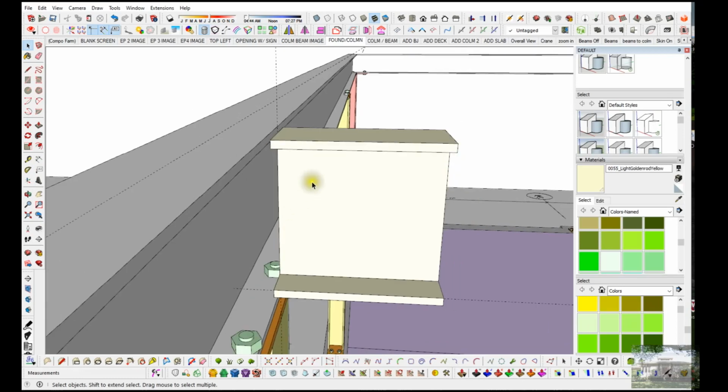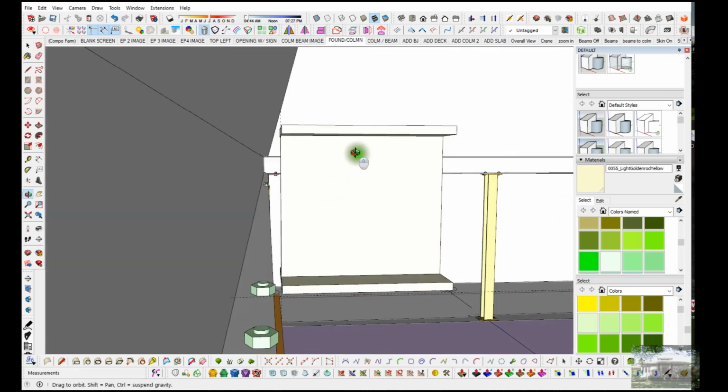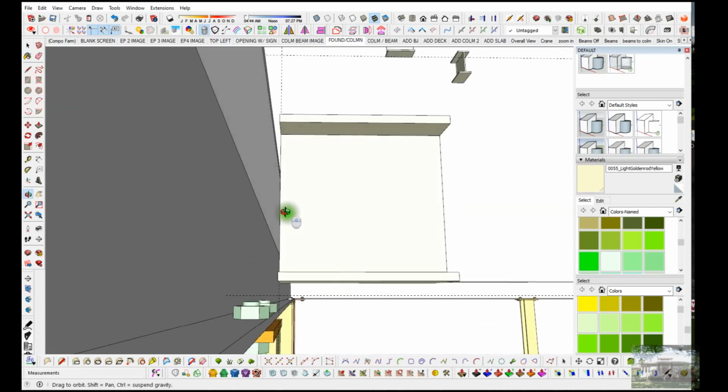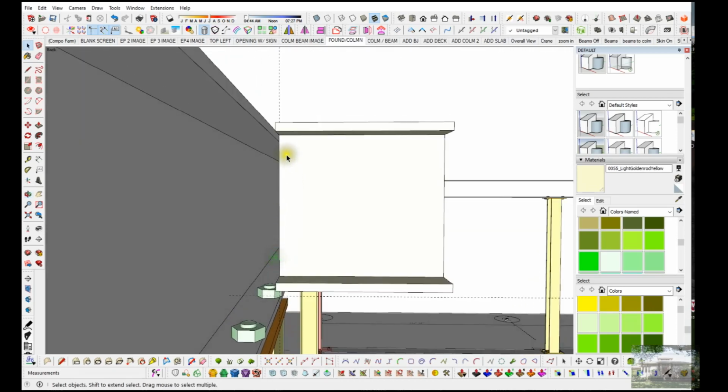What I need to do is cope this beam. As you can see, there's a space. So this beam has to be cut out from the top down. This part is going to be short anyway. It's short of the bottom of the perimeter beam anyway. So what I need to do is be able to get this web over to that web. What I would do is check and see that there's 3¼ inches of that flange sticking out.